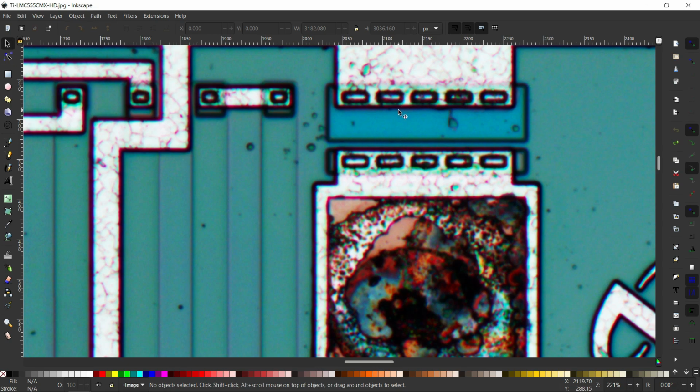If not, they will call this an ESD diode, but this is a stretched drain device, because see, the distance between the source terminal and the drain terminal is a very large distance. So it is a kind of ESD diode, okay, a stretched drain ESD diode.